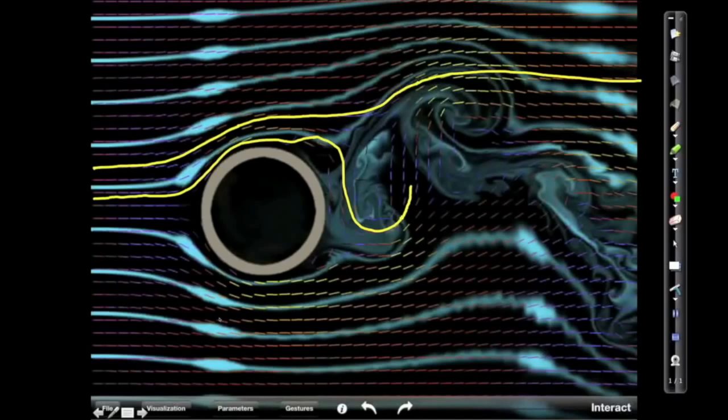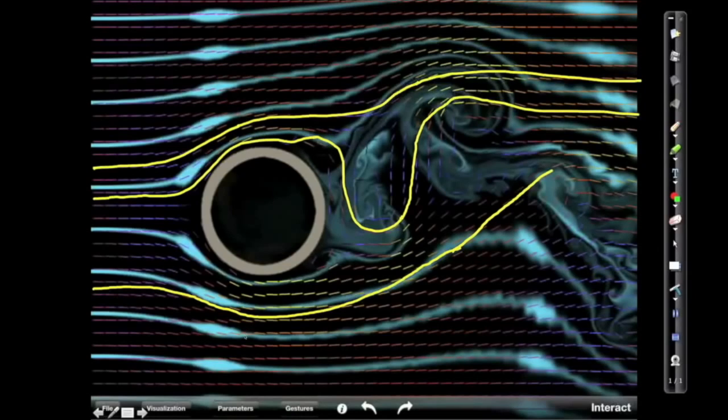This comes up through here, and I'm locally trying to stay tangent to these velocity vectors. Let's take one just to finish down here on the bottom. So we can see that those smoke lines that are in here, and with those blobs on it, were not at all streamlines, not in any general sense anyway. Here you can see I'm crossing over these smoke lines back here, and they're not coinciding.